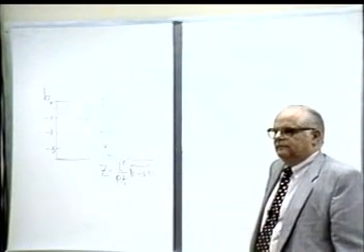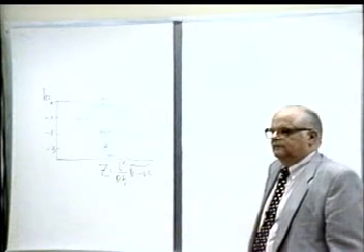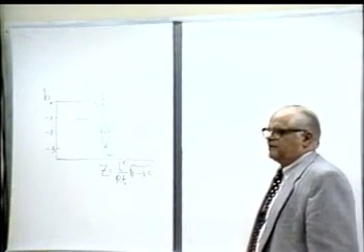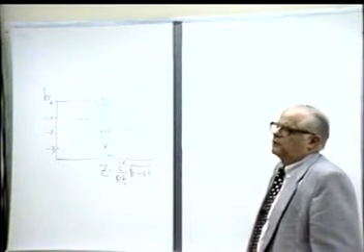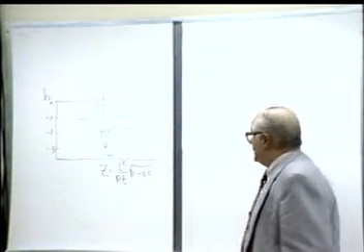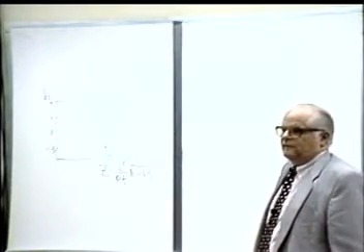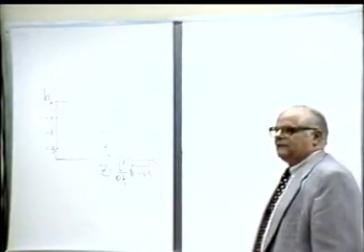How much is beta over alpha in your analysis? Koiter put it to be 1. Yeah, for membrane pre-buckling, if you use membrane pre-buckling, beta and alpha are both 1. Yeah, but how much? In my analysis, I had cases where beta was negative, so it varies with the shapes.